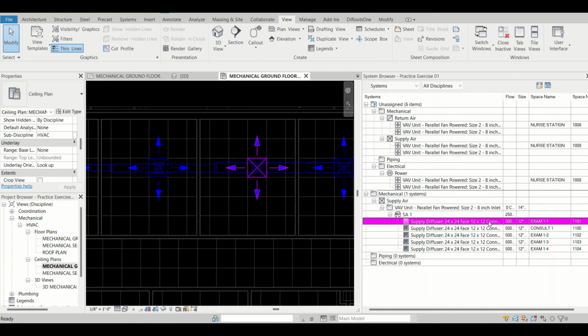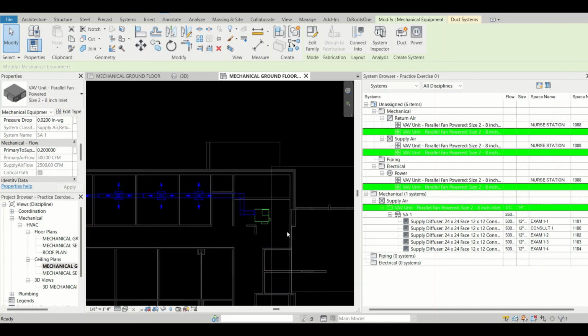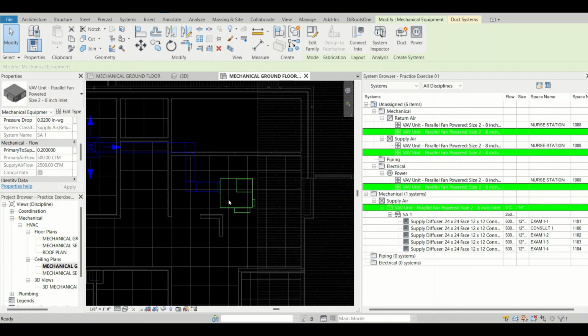That's very useful. And why are multiple VAVs showing? Because we know that for each VAV mechanical equipment we have electrical connections, and we have three types of connections: supply, return and exhaust. So if I select any VAV, it selects all these because they are a single one only, and in Revit also it got selected. It is showing as per the connectors aligned with this mechanical equipment. So do not get confused that there are four VAVs; it is a single one only.